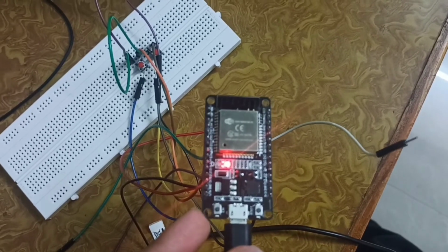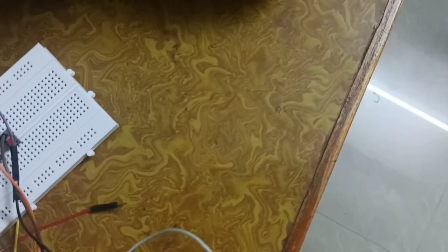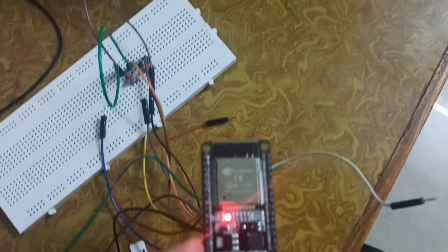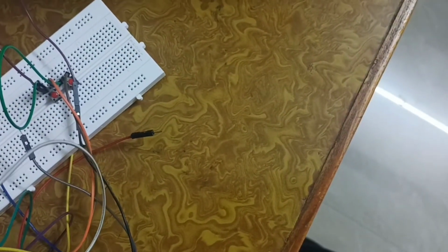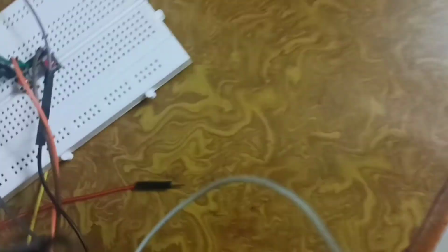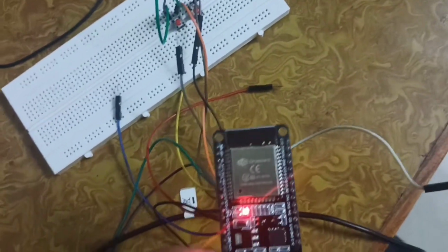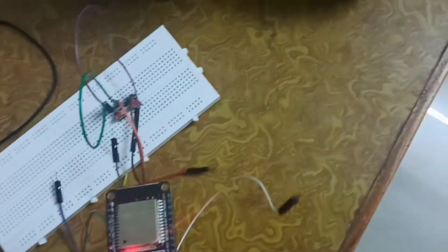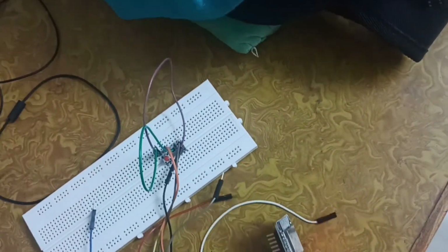Good morning. Today we are going to see how to design an ATM machine using ESP32. Here we can see the connections, where pin numbers 32 to 13 are touch pins and are used as input pins, and here pin number 4 and pin number 15 are used. In between these pins, pin number 26 and pin number 27 are not touch pins, and thus we have connected push buttons so that we can take the input from the user for those pins.